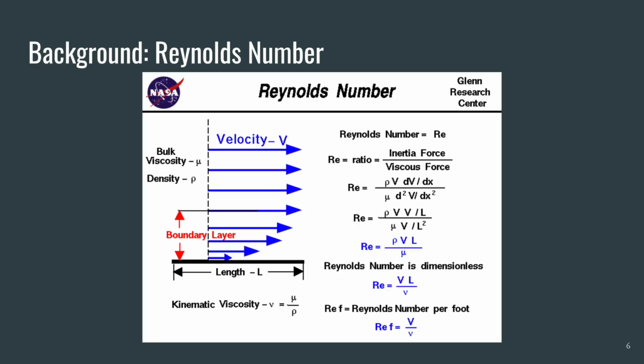Many important concepts were used to develop the background of this experiment, including Reynolds number. The Reynolds number expresses the ratio of inertial forces to viscous forces. For airflow past a circular cylinder, the drag at moderate or high Reynolds numbers is primarily the pressure drag.